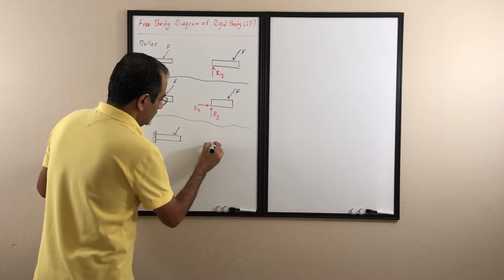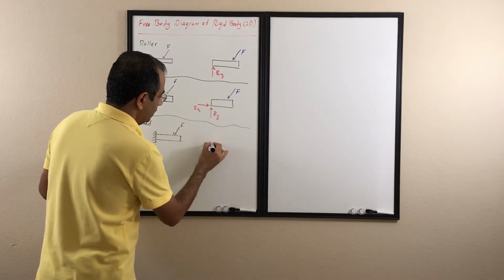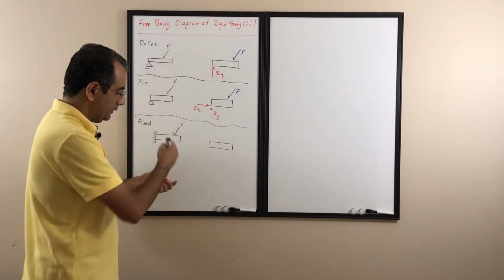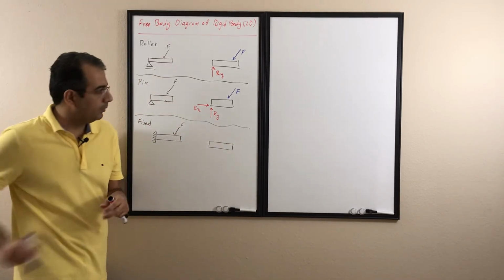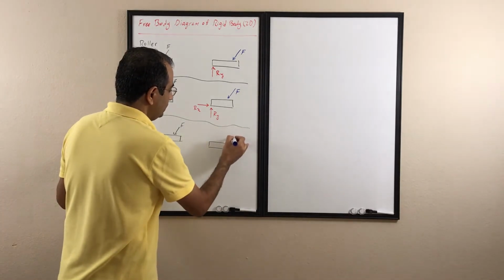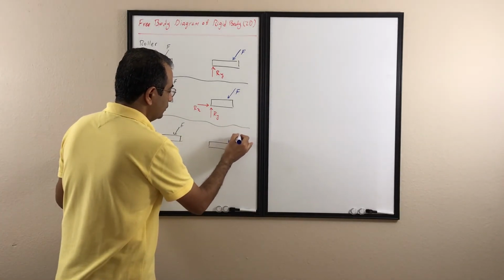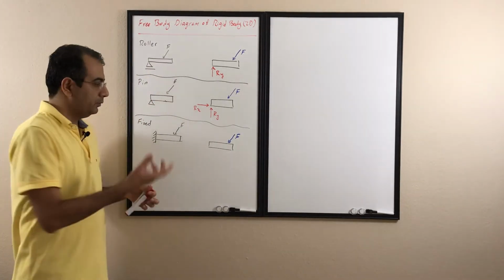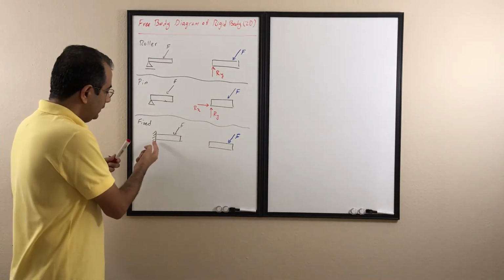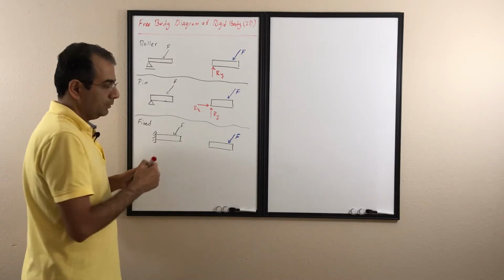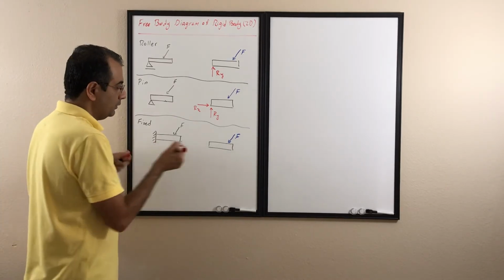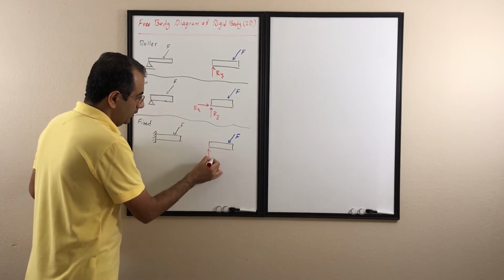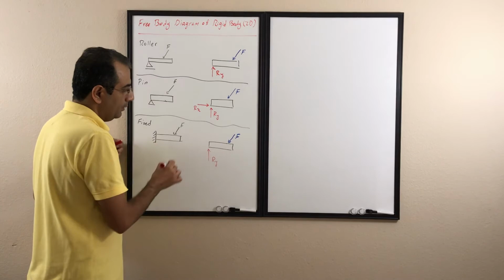So when I want to draw that, again I draw the object itself, disconnected from any part. Then I add external forces that want to move it. And then I start to add the reaction forces that want to keep it in place. This one doesn't let it go up and down, so I have to add the reaction force RY to stop that point going up or down.